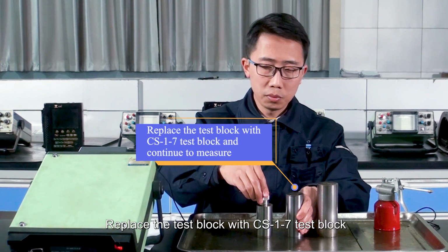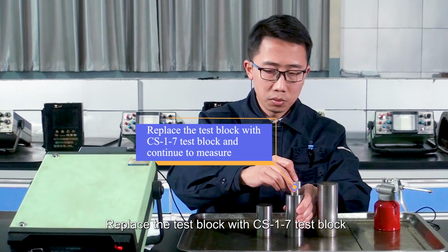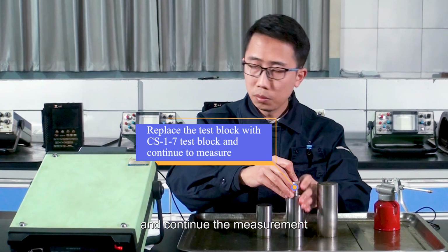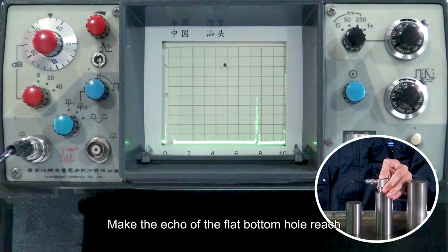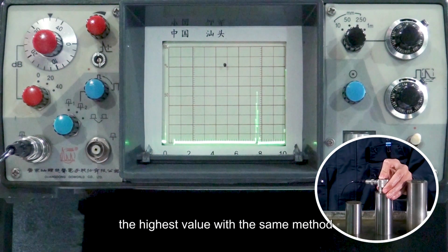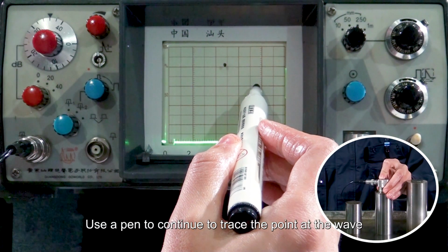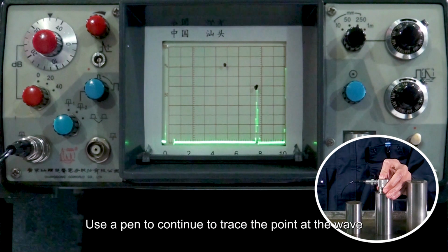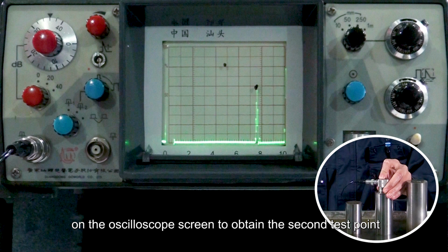Replace the test block with the CS-1-7 test block and continue the measurement. Make the echo of the flat bottom hole reach the highest value with the same method. Use the pen to continue to trace the point at the wave peak position of the flat bottom hole on the oscilloscope screen to obtain the second test point.